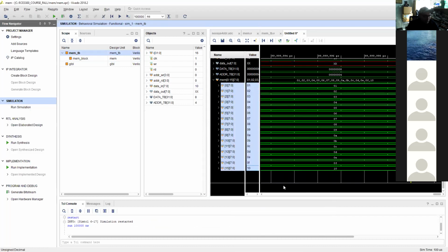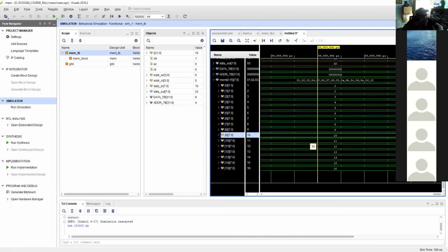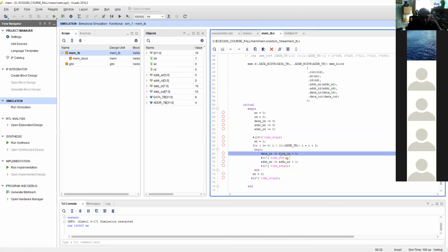Yeah. Hello? So you understand what I'm doing, right? I don't want to fill the first location with 0, so I tricked the counter. I said, go count 1, because I don't want 0, right? But in that case, increment the address. Then the address came after 1, so that means the data n is 1 and the address will point to 1 there. You understand? So I took more time, if you notice, to do this.